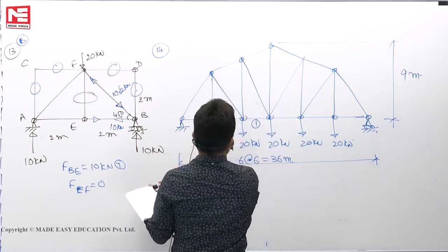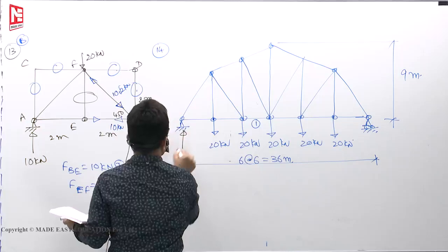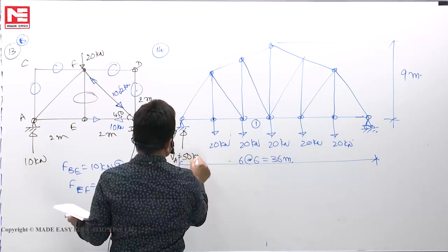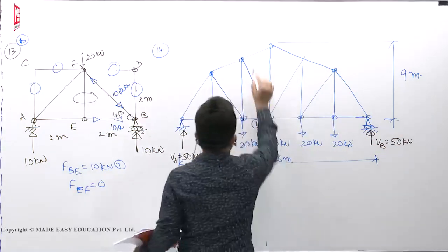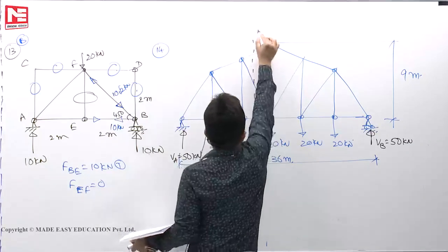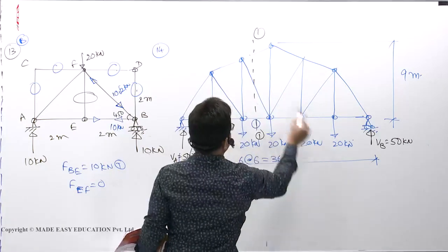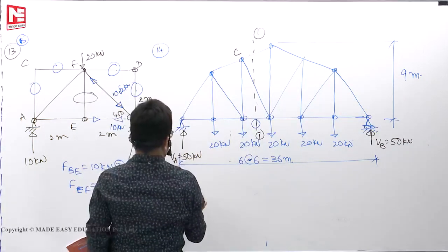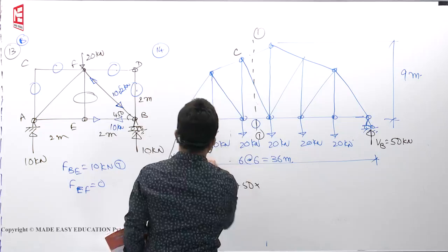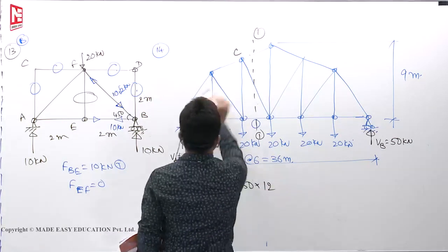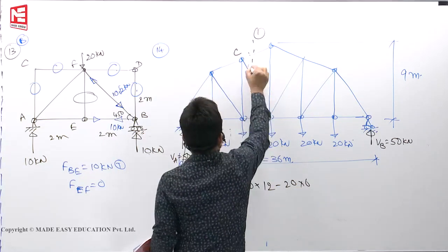Okay. Now we wanted force in the member 1. See here, symmetry is there. Total 500 means here it is VA, let us say 50. VB is also 50. First support reactions, cut by 1, 1. Look left side. The unwanted members are meeting at A, B is over C. Take moments of all forces at C. Sigma MC is equal to 0. Plus 50 into 6 plus 6, 12. Plus 50 into 12. Minus 20 into 6. This is 0 over. These two will give 0 moment.